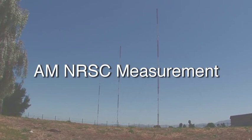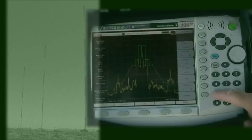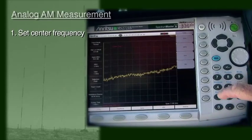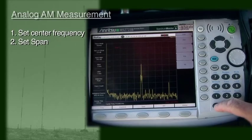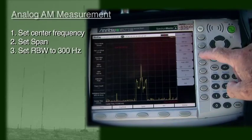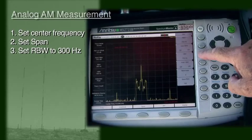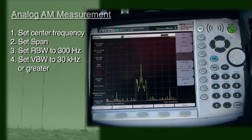Here is how to do the measurement for analog AM. After you preset the instrument, set the desired center frequency. Then, set a span of 200 kHz. Set RBW to 300 Hz. Set VBW to 30 kHz or greater.